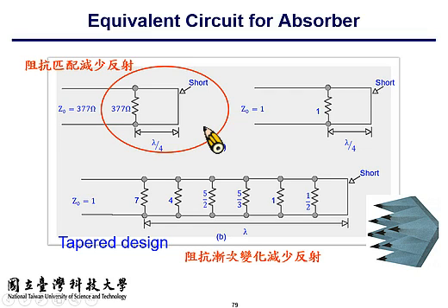Okay, so here is an example of a one-wavelength design. If this is 377, this one is 185, 377, something larger than 377, and even larger. So with this taper structure, multi-layer taper structure, you can achieve broadband matching for propagating waves. All right.